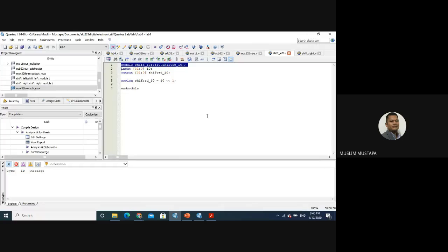All right, so now we are going into lab 4. If you guys remember, the task is asking you to modify the existing ALU code that I gave to you guys. The things you need to modify are to add shift left and also shift right. The first thing you need to do is complete the shift left and shift right code first. So you need to take the input from A input, just one input, and shift it 1 bit.